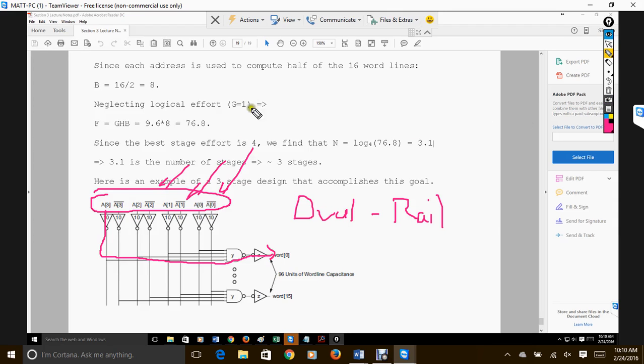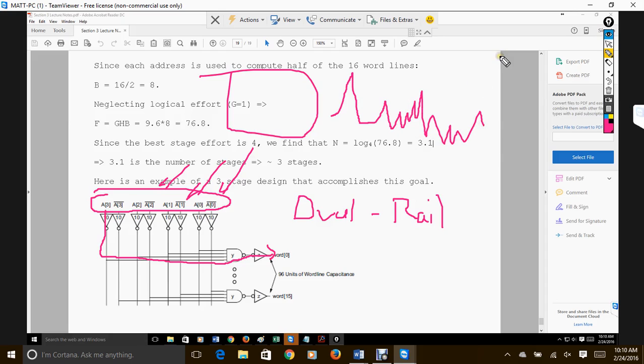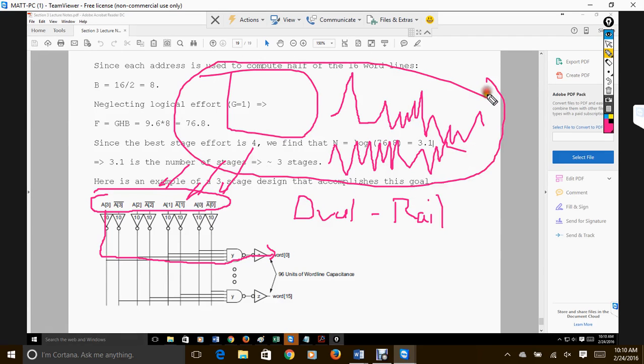So that means I switch, and I'm activating the other ones, right? So what's happening is, now you're thinking this gains area, but what's going to happen is, if you track the power consumption, you have some sort of spike every time you switch. And if you're only switching PMOS and NMOS, especially if you have different logics in AND or OR, we calculate they're all different. But if you're having a pull up and pull down, that means every time it's going to be very, very similar. And so what can happen, suppose if you have smart cards, the cards with pins, you can actually put the pins on there, get one of these oscilloscopes, and if it's poorly designed, you can use these differences in power spikes to obtain your cryptographic key and break into the person's car without having to deal with any of the software.